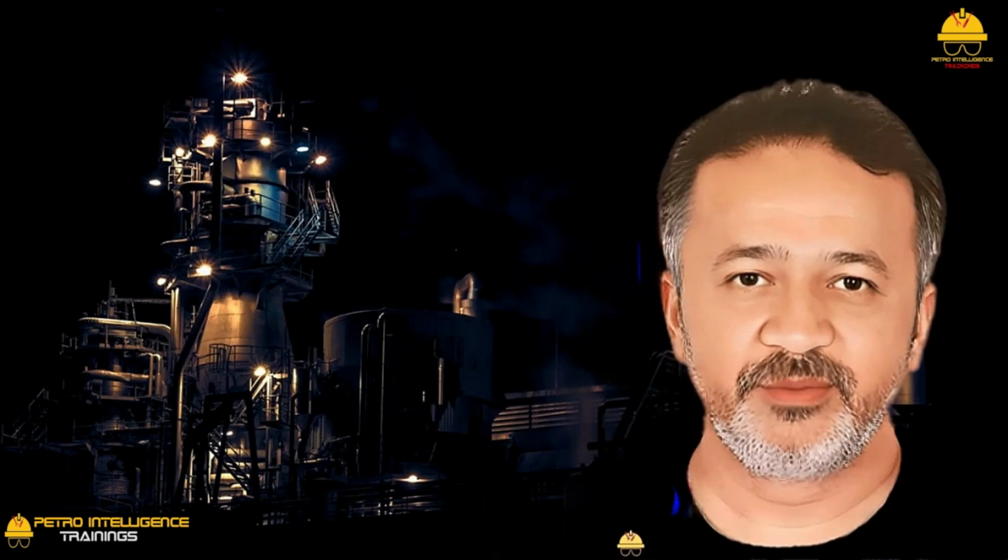The surface condenser. There is another problem with the barometric condenser that did not become apparent at first. When the British Navy decided to convert from sail to steam, this problem was immediately obvious. While steam can be generated from seawater, it is far better to use fresh water, especially if one wishes to generate high-temperature, high-pressure steam. And as freshwater supplies are limited at sea, it would be great if the condensed steam could be recycled to the boilers. But the cooling water supply to the barometric condensers was naturally seawater, which mixed with the steam condensate.